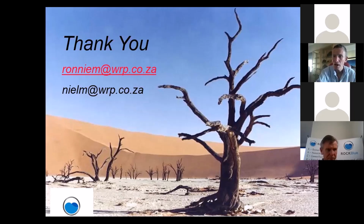And the minimum night flow is, in my view, one of the most important factors that you can look at when managing leakage in a zone. It is by far the best indicator of leakage in a zone. And it's good to be able to get an estimate of what you would expect so that you can determine whether or not you have a problem and how big that problem is. So it's a very good indicator, and it deserves a lecture on its own.